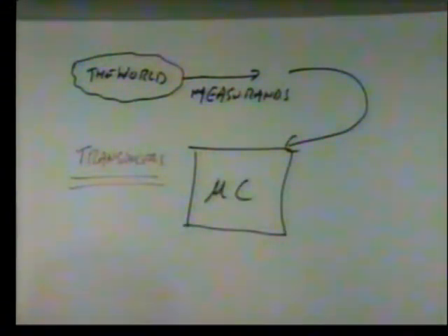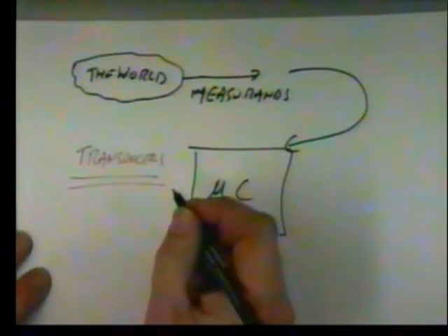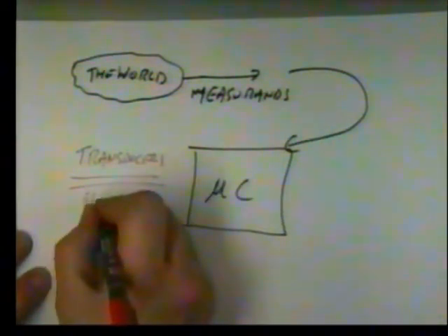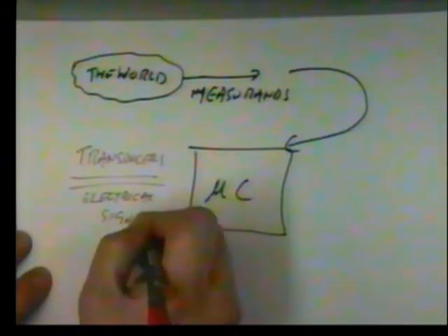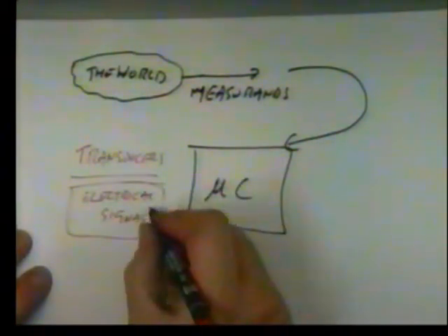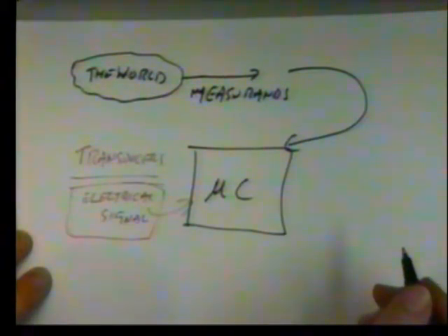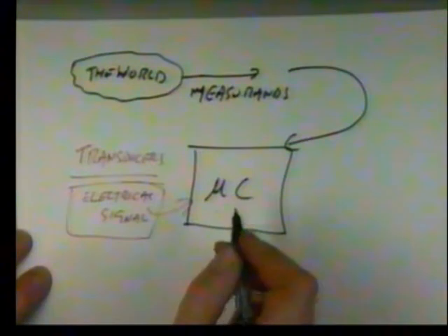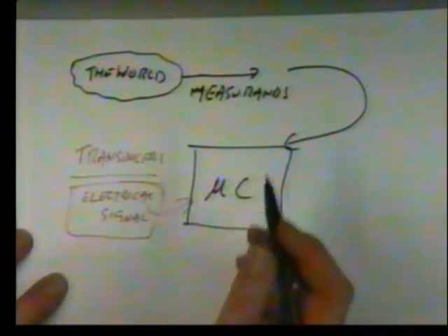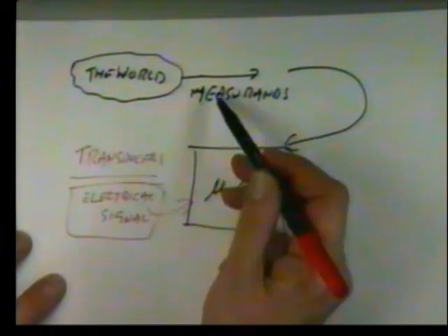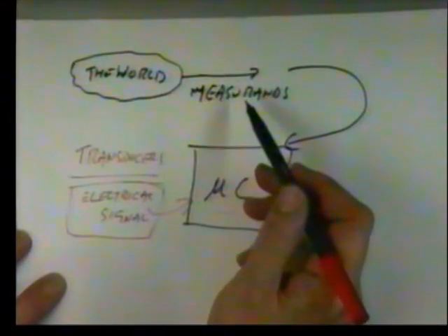So what is a transducer? A device that converts one measurand into another measurand, ultimately with the view of getting out an electrical signal. Why electrical? Because we need to get this information into our computing system. And there are a variety of tools we can use to convert the electrical signals into numbers that the microcomputer can use. So, rules about transducers: they convert one measurand into another measurand with a known mathematical relationship.